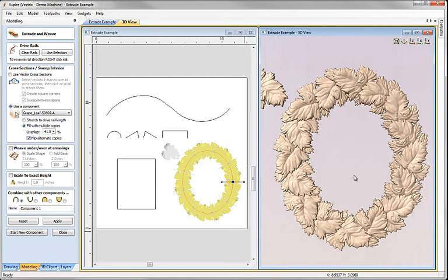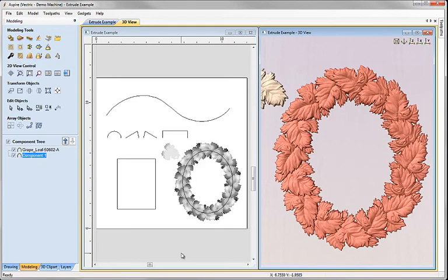So this is a very, very powerful function. We're still using the same function that we use to extrude all those different vector cross sections along our drive curves. In addition, we can actually use multiple drive curves as well, which we'll see in a moment when we start to look at some of the options we've got in here for getting the shapes to weave. At this point, what I'm going to do is just hit close. You can see that will create a new component for me, which is represented by all those individual leaves. This is not a group, this is just a single component, so I could not get back to the individual constituent parts of that particular set of leaves in this case.